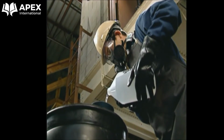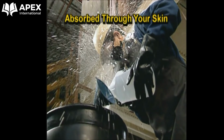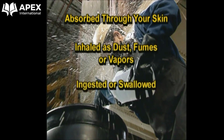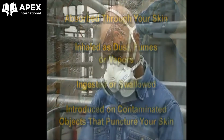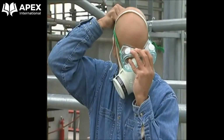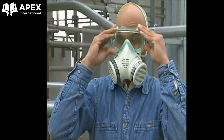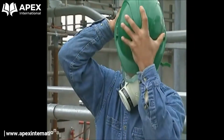Hazardous chemicals have 4 ways of entering your body. They can be absorbed through your skin, inhaled as dust, fumes, or vapors, ingested or swallowed, or introduced on contaminated objects that puncture your skin. To reduce the risk of exposure to hazardous chemicals, you must wear personal protective equipment, or PPE, that is designed and tested for the chemicals you're using.